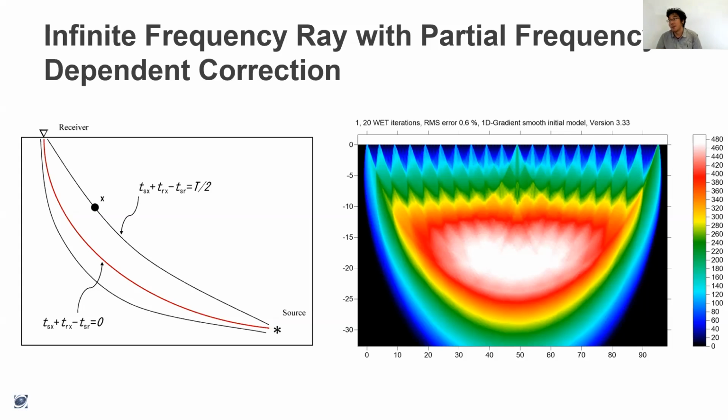Causes of waveform inverting from one geophone to another. Usually that's because you plugged in the geophone backwards. That, I think, is the only common time I've seen the waveform inverting.